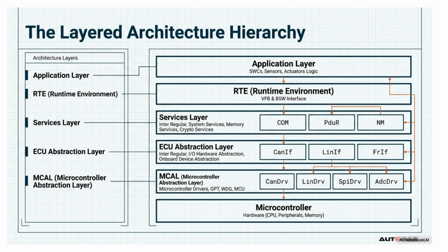Within the BSW, the services layer provides bus-independent management. The ECU abstraction layer offers standardized interfaces for bus-specific modules like CAN-IF or LIN-IF, and the MCAL contains the low-level drivers that have direct, register-level access to the microcontroller's communication peripherals.